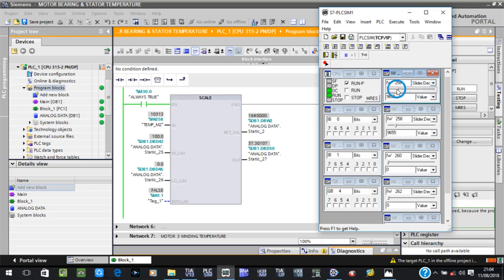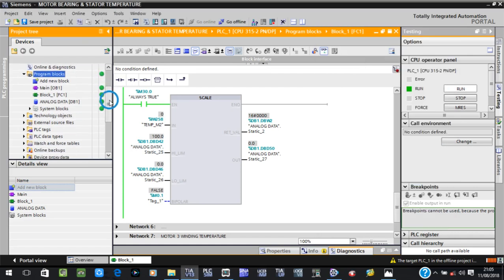Now, where your motors are located and where your CPU and HMI are located might be two different locations. You want a system which is called a decentralized system, where you have a communications interface, which is your Profibus or your Profinet. So I'll show you the networking just after I'm done with simulating the HMI.